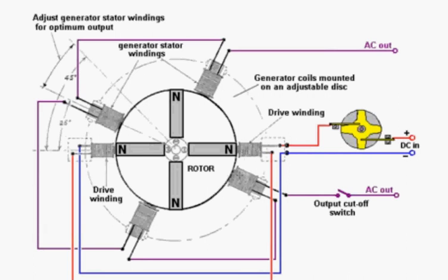The same is done for the pickup coils. The magnet comes up, and as it's approaching the coil, you get an output of electricity through the coil around the core. And what happens is, when it reaches the coil itself, the switching disconnects the core coil, and that reverses the magnetism of the output coil, which pushes the rotor on its way.